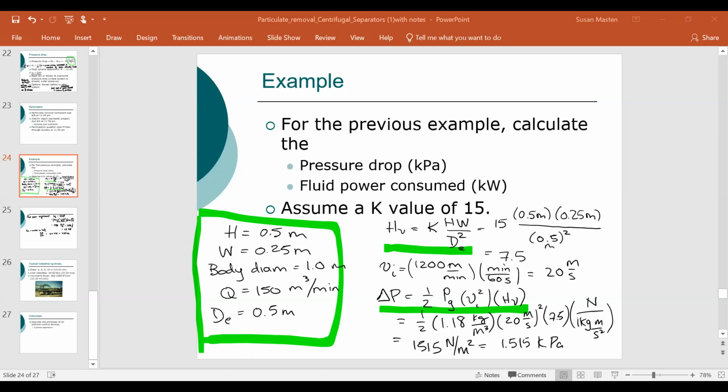So electrostatic precipitators can be used for a wide variety of types of materials. It's a versatile treatment process. They can be used for both dry dust or liquid droplets. They tend to be used for liquid droplets where you have a very sticky material, to prevent that material from sticking onto the collection devices.